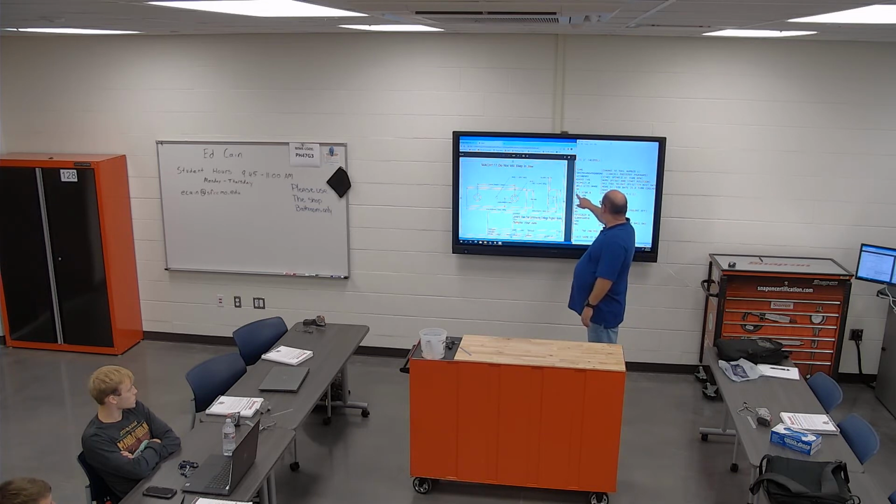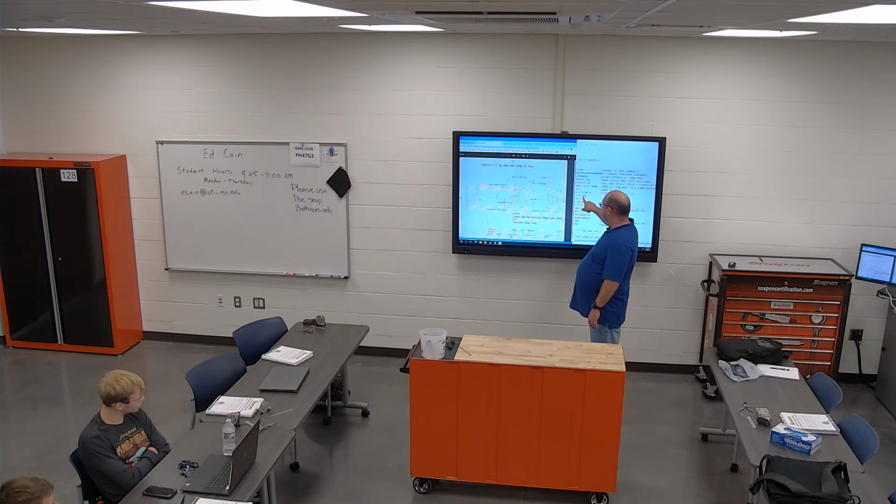And then the next one is a feed rate. And this doesn't even have to be in here. You don't have to put the feed rate every line. You can just go back and forth. So X of negative 5.5, feed rate of 60 out. That's the first one. And then a Z of negative 100 thousandths. So it's going to drop 100 thousandths. Then it's coming back to this side of 5.5. So we're just going back and forth.